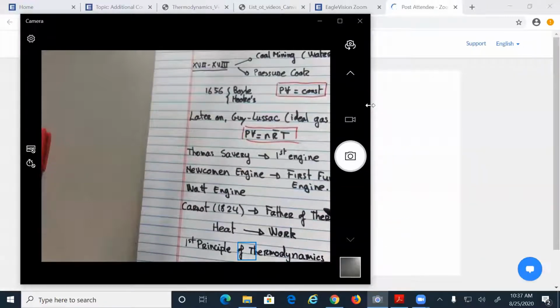So there was a deficiency in the theory of the first principle of thermodynamics. Thermodynamics needed to find a way to define the efficiency of the engine. And that would be pretty easy. Generally, when you want to find if something is efficient, the amount of work divided by the amount of heat will give you the efficiency. Let's say you have 100 kilojoules of heat and you get work of 50 kilojoules; dividing the work by the heat you put in gives 50% efficiency.